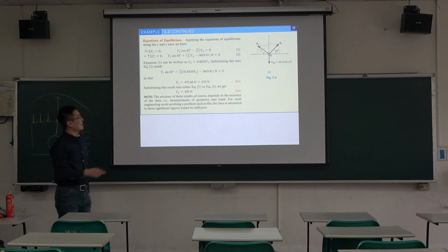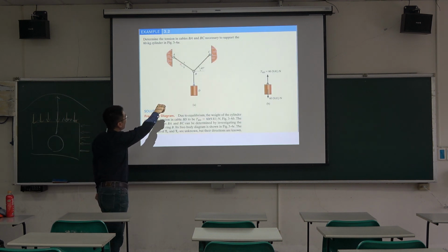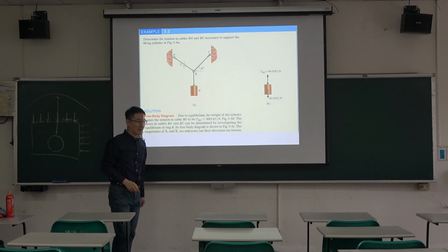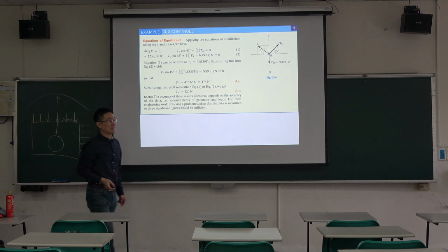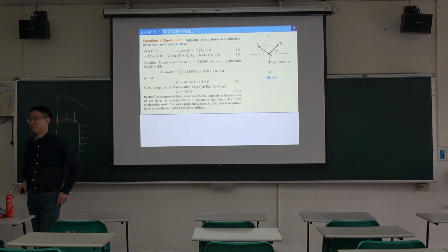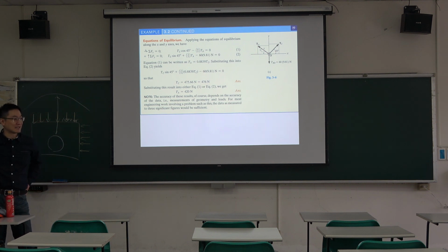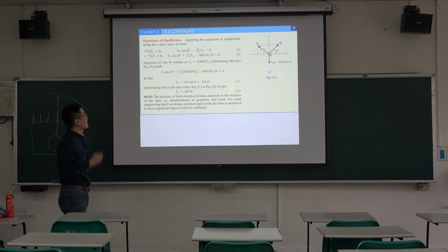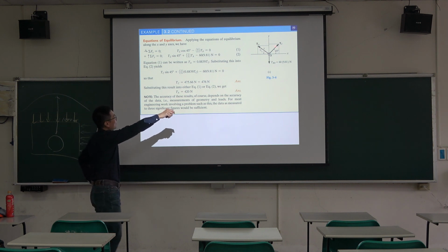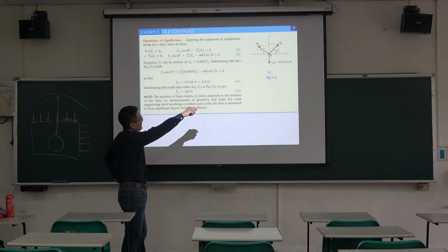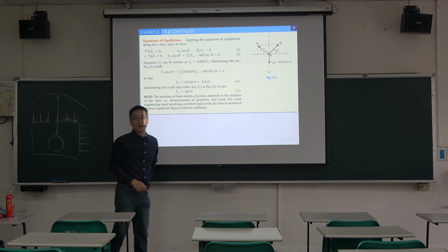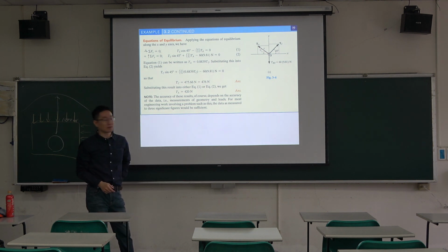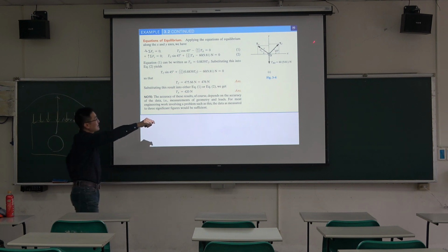The same, these two are also cables, so you can see they lift away from the joint, because a cable can only provide tensile force. And for these two forces, we already have an angle, so we can work out the vertical and horizontal components.